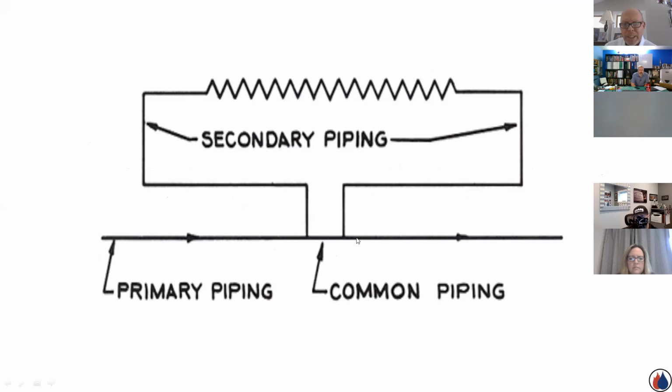I put both standard T's close together. He referred to it as common pipe. Flow in one will not cause flow in the other circuit if the pressure drop in the common pipe has been eliminated. There's not enough of a pressure differential for the water to flow through that secondary circuit. He eliminated it.